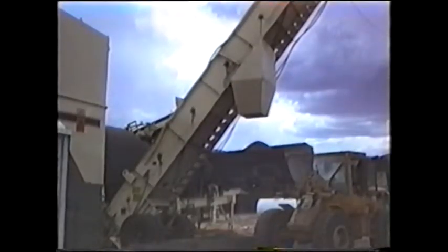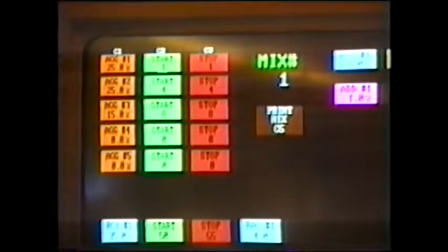Several features were incorporated to minimize the amount of material waste normally associated with drum mix production. The primary features are in the mix design itself. Impulse will store up to 20 mix designs. Each formula contains a percentage of each material and a programmable start-stop time for each material. This gives complete control over the staging of materials for each mix. Additional mix storage capacity is available as an option.